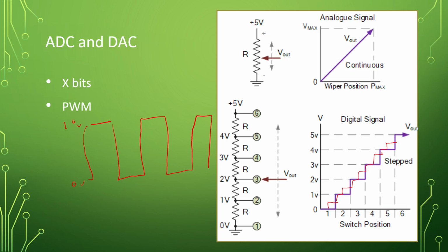This is with an inductor, and the pulses wouldn't be as noticeable. So inductors resist the change of current flow. Capacitors are like a battery, so those would charge up some. I would do an inductor and then a capacitor if you really needed to help smooth things out. But that's basically how we'd be doing this with a digital to analog.